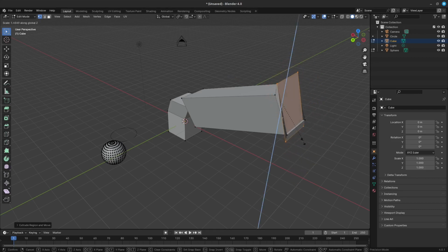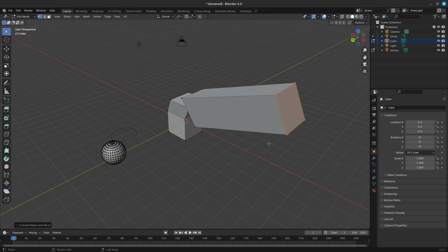The extrude tools differentiate in how the new geometry is connected in itself. Only the border loop gets extruded. The inner region of the selection gets moved unchanged with the extrusion. Next, what is extruding a manifold?